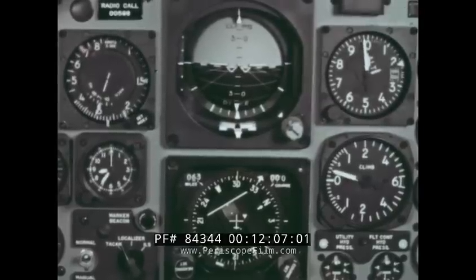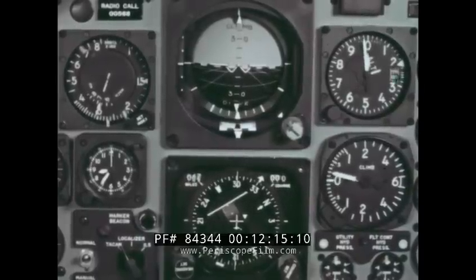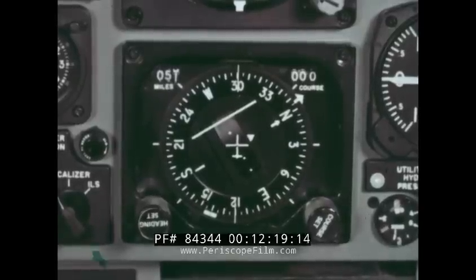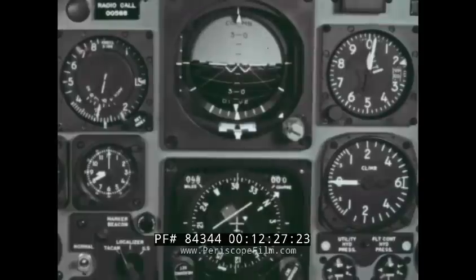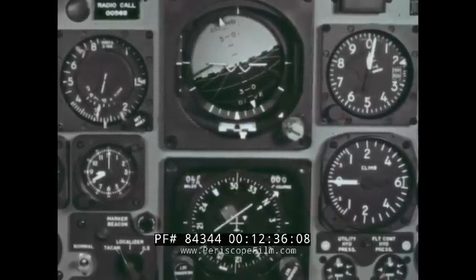The position of the aircraft symbol with relation to the course deviation indicator clearly shows your interception angle. When you are within 10 degrees of your course, the course deviation indicator will start to move. Depending on how fast it's moving, turn to roll out with the course deviation indicator lined up with the aircraft symbol.